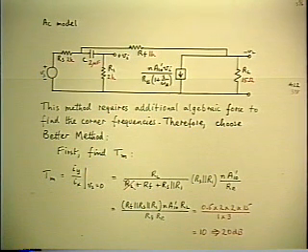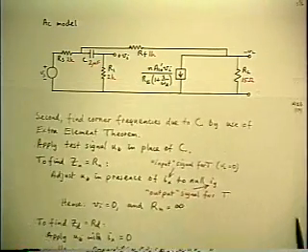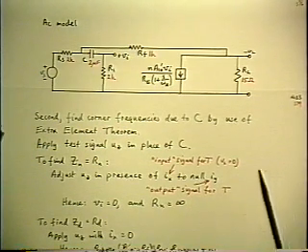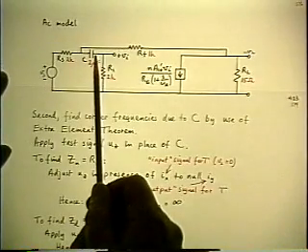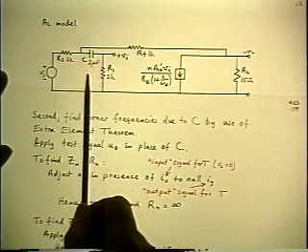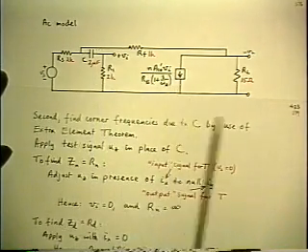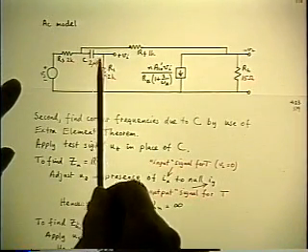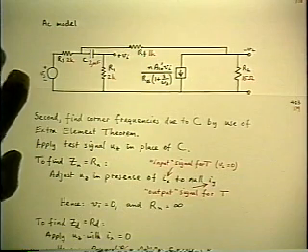Now we have to replace the capacitor. Again, we can do it all in our minds, applying the correction factor for the theorem. If we replace the capacitor with a second test signal, we have to calculate two driving point resistances, Rd and Rn. Rd is found by applying the test signal, single injection, and making the input 0.